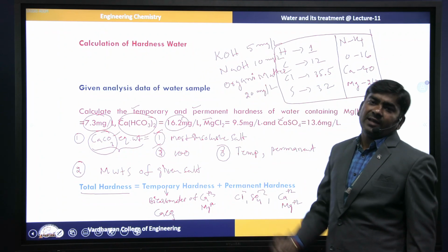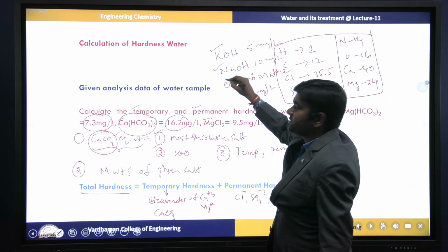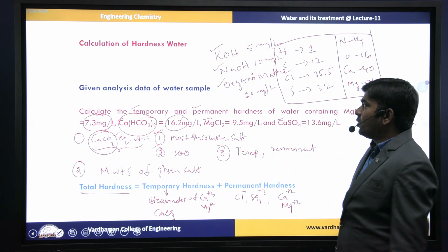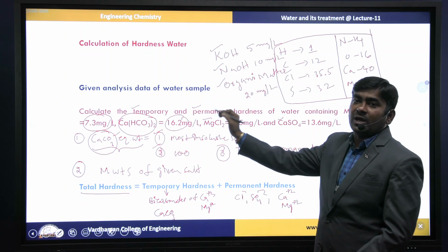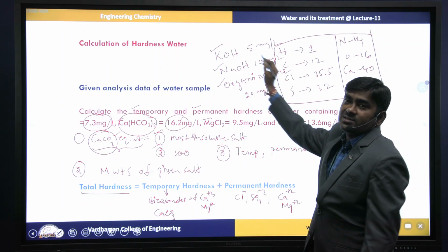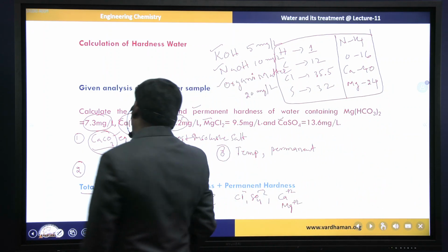If you observe these salts and organic matter, don't go for calculation or conversion into calcium carbonate equivalents, because they will not contribute any hardness to the water, right?